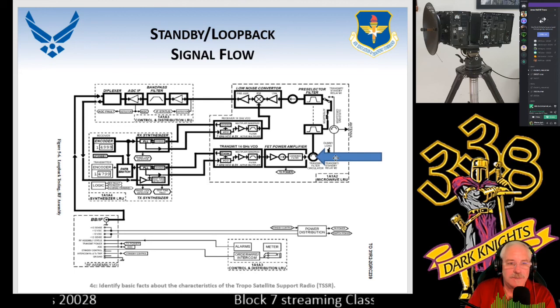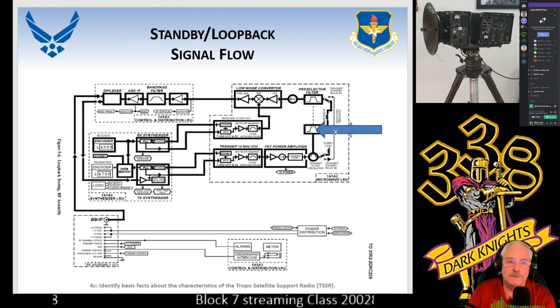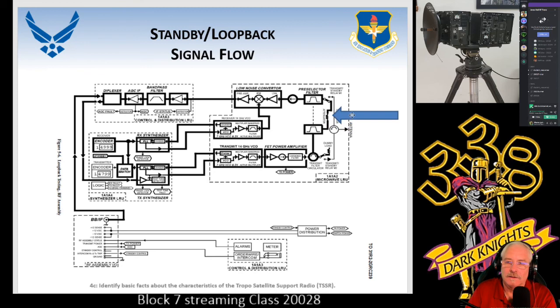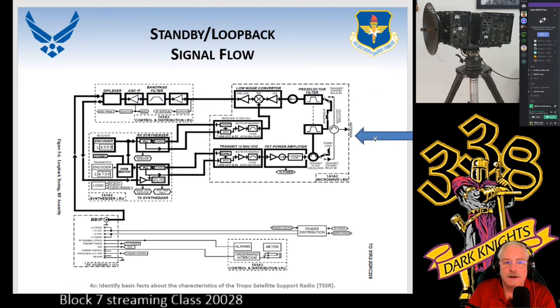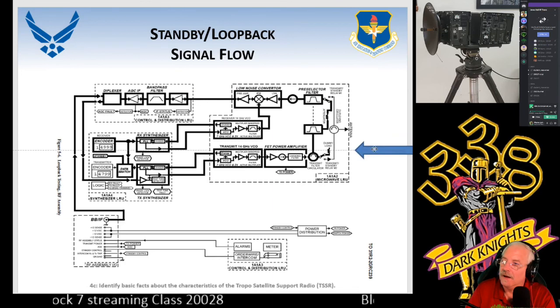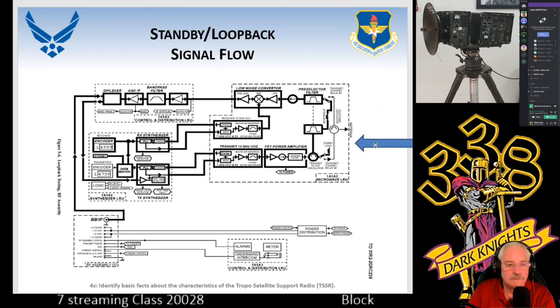This transmit filter circulator is going to send the signal up to this pre-selector filter because it's dual, up through the attenuator, and it's flipped this switch in the down position. It goes through the whole receiver section. None of it goes out the antenna. None of it. So that's how the signal is able to get back around for loopback.